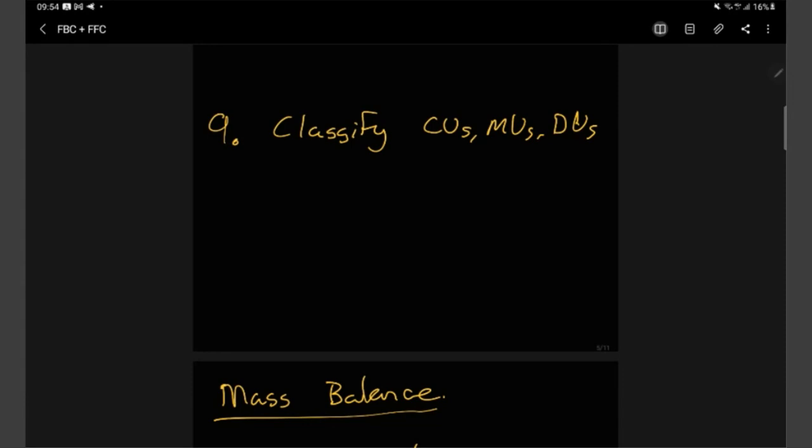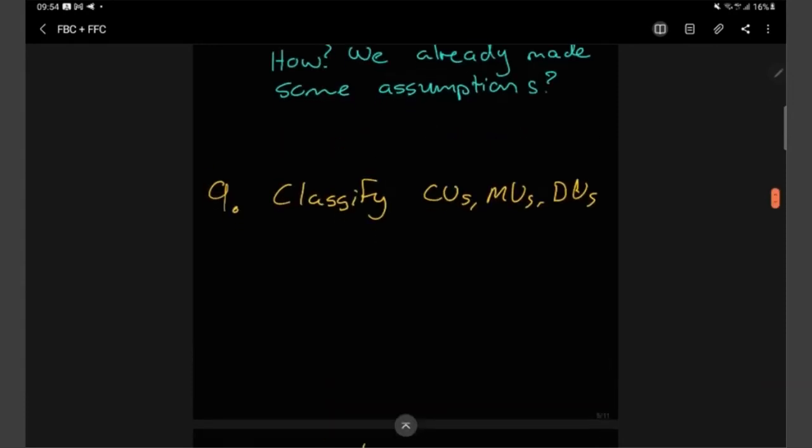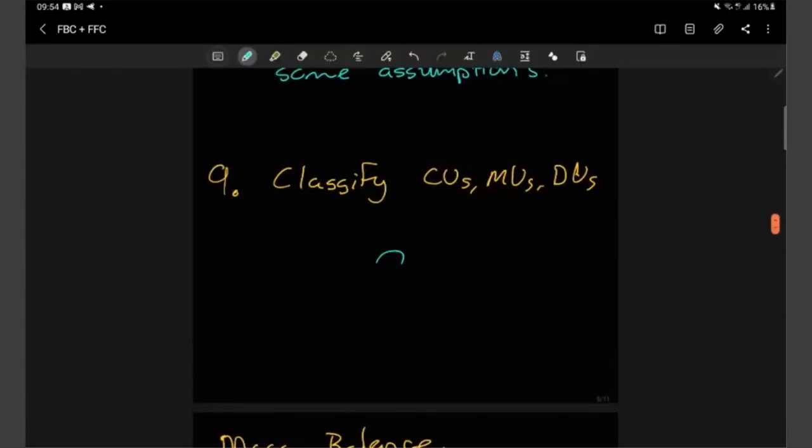Let me quickly draw this. If we have, let's say, a boiling tank or something like that, where we introduce some energy and we supply a vapor to a downstream process, the pressure here can be disturbed by a downstream process.